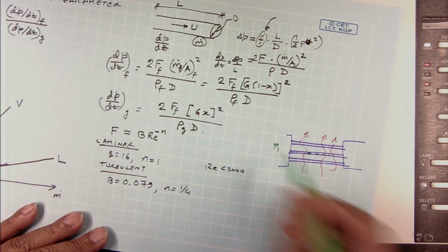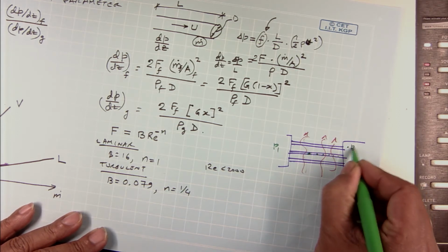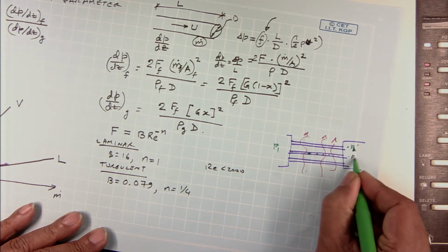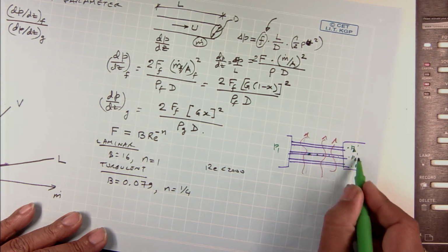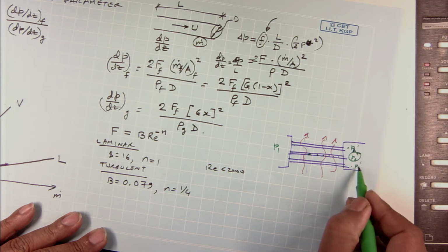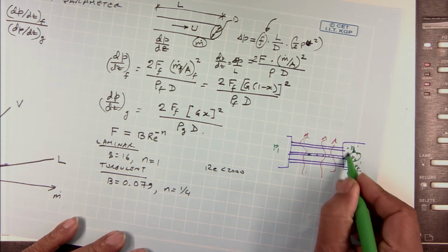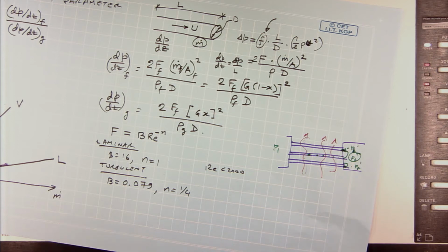So, I am coming in with a uniform pressure P1 over here, but if I look at the local pressure here, P2, let us say PA prime, PB prime, PC prime. Now that this one has a lower pressure drop, my PB prime will be higher than PA or PC. Okay, what will that cause? It will cause a part of the flow to start pushing back on these flows, because that is at a higher pressure. Does that make sense?